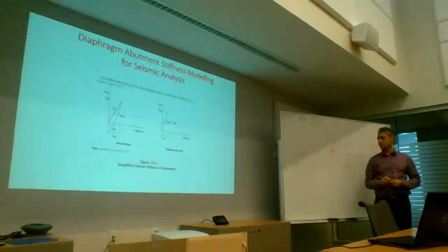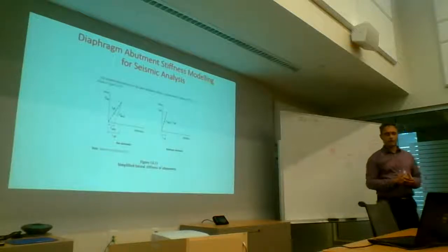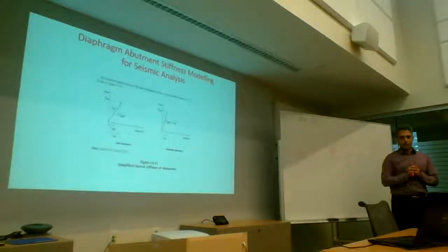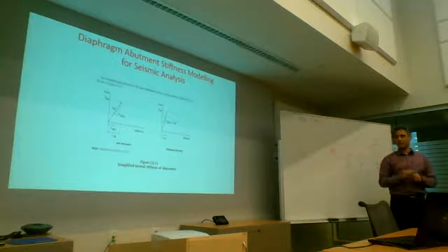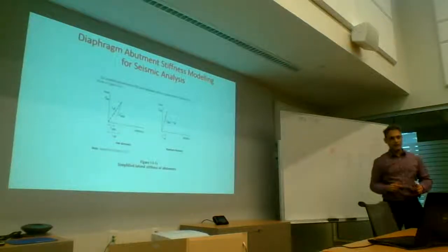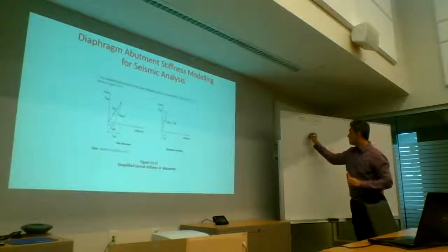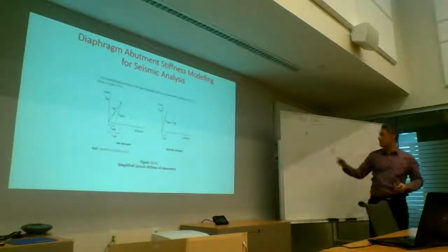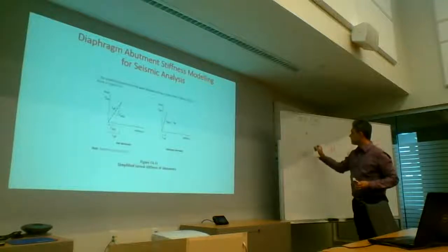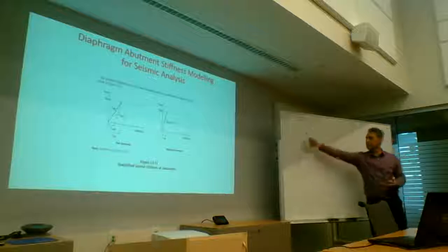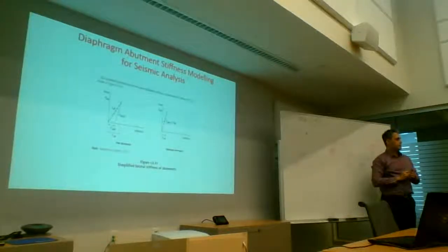You run your analysis, and you see, oh, there is very little deformation. You're super happy, this is working. And then you look at it a bit more closely. You look at the abutment spring that you've put in there with the stiffness, and it's showing a force up here, and this much displacement, fine, but it's showing a load up here. Well, the abutment cannot develop that much load. So what you just got is artificial, right?